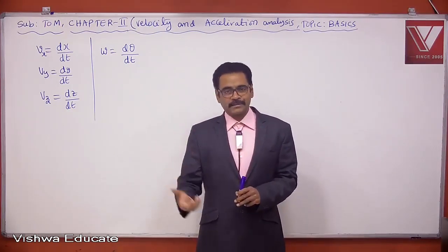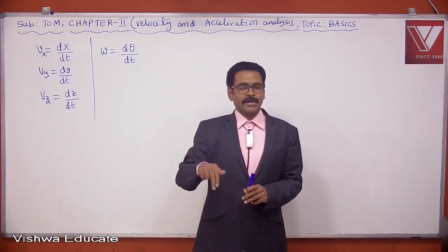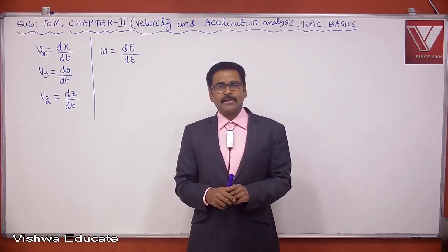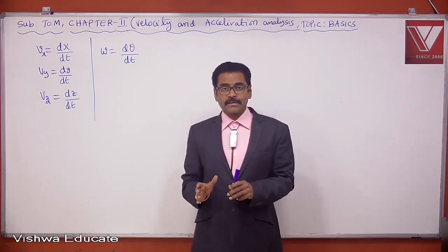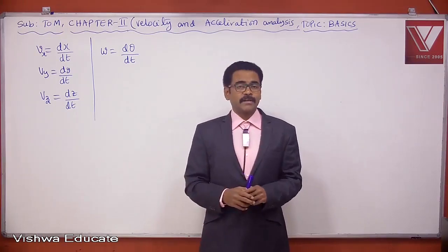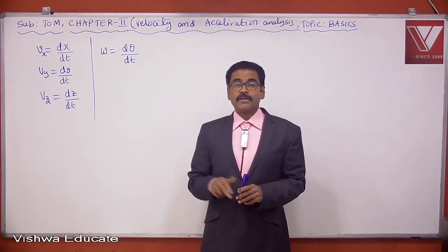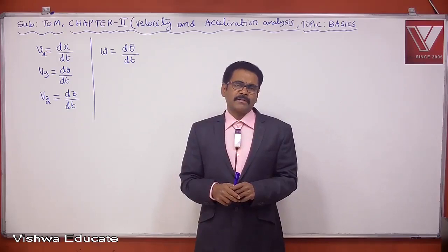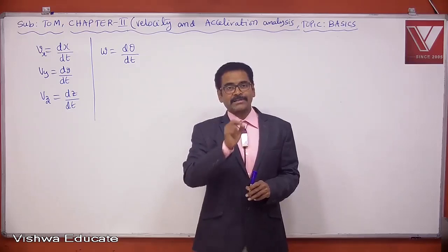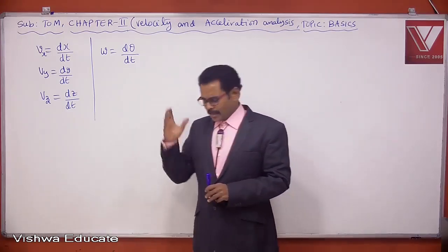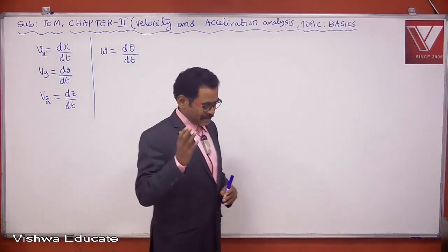For new mechanism, fixing. So either fixing of velocities or calculation of velocities is called velocity analysis, right? I already told why we have to perform velocity analysis. One reason is different applications may require different velocities. That is why we have to fix certain range of velocities in view of requirement and need. Second requirement is, we have to perform velocity analysis for performing acceleration analysis. Before performing acceleration analysis, we need to perform velocity analysis.